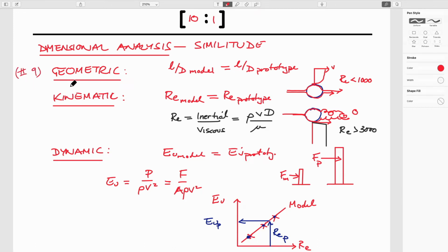the topic was dimensional analysis or similitude. And the idea is that relative to those videos we looked at, where you use a wind tunnel as one format of the experiments that you might run, you can cover all the parameter space with a minimum number of experiments if you follow a relatively straightforward procedure. That is called the Buckingham Pi theorem. It allows you to define exactly what the non-dimensional parameters would be.